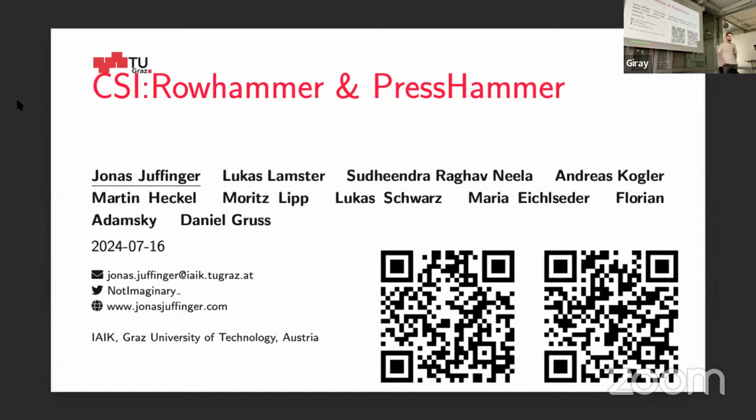They have some aging circuit in there that always runs while the CPU is running, and they measure the latency of this circuit on every boot to know how much the transistor has already aged, and then modify the guard band based on this aging prediction. It's sort of like a sensor for that. They just have a lot of inverters and measure the latency to know how long the CPU has already been running, how much it degraded. And maybe they do something like that in DRAM.